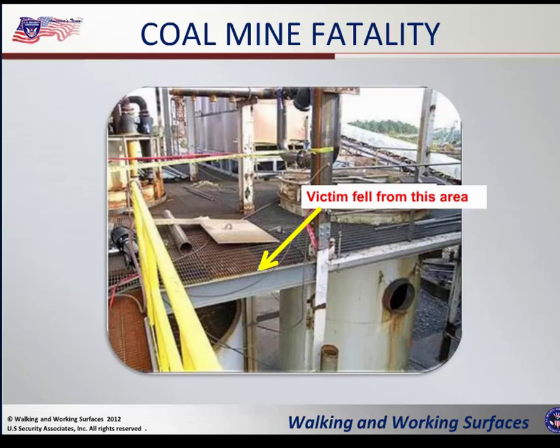After the workday, he and his coworker were putting away his tools. His coworker had gone down to turn off the oxyacetylene tanks and came back to find this coworker had fallen 16 feet to his death. Okay? So this is what we're talking about. Know your areas. Know the areas that need to have handrails and toe boards, so that if you see something like this, you can bring it to your supervisor's attention.